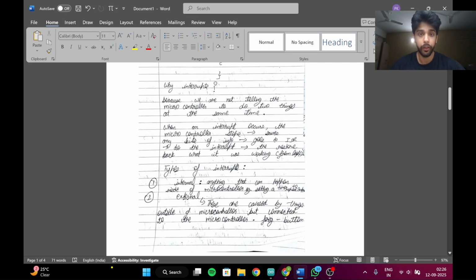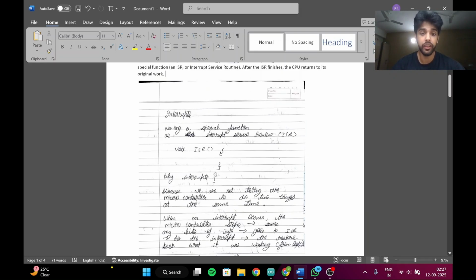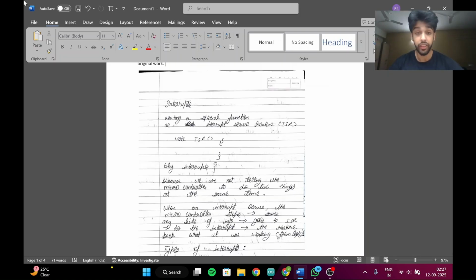In the previous task, we studied the external interrupts, but what's the difference here is external interrupts are those interrupts that are caused outside of the microcontroller. For example, the LED button press. It's an external interrupt because it comes externally from outside the Arduino, and the Arduino processes it and then follows the interrupt. However, the internal interrupt is triggered by an event generated inside the Arduino.